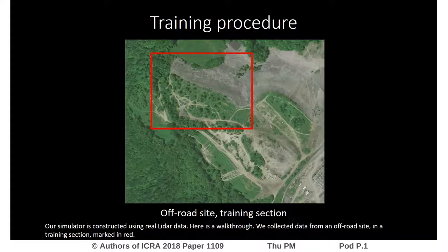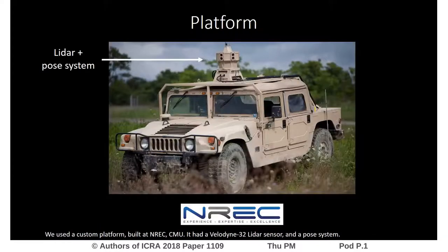Our simulator is constructed using real LiDAR data. Here is a walkthrough. We collected data from an off-road site in a training section marked in red. We used a custom platform built at NREC CMU. It had a Velodyne 32 LiDAR sensor and a pose system.